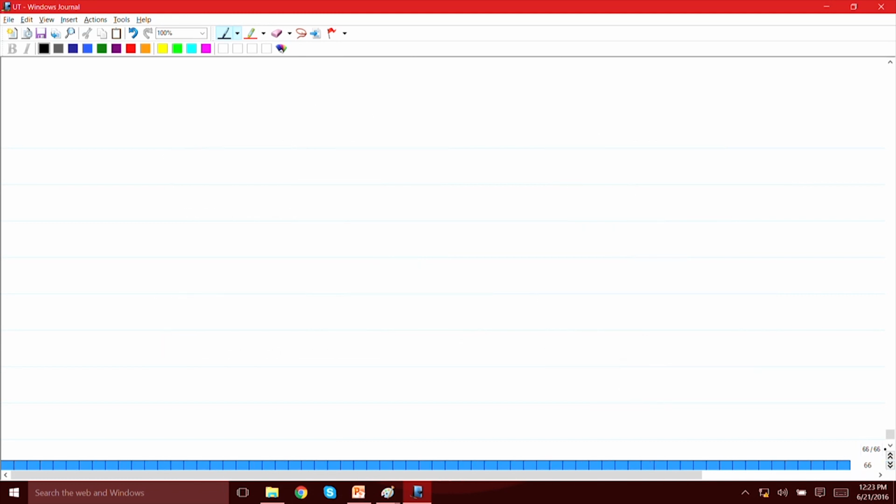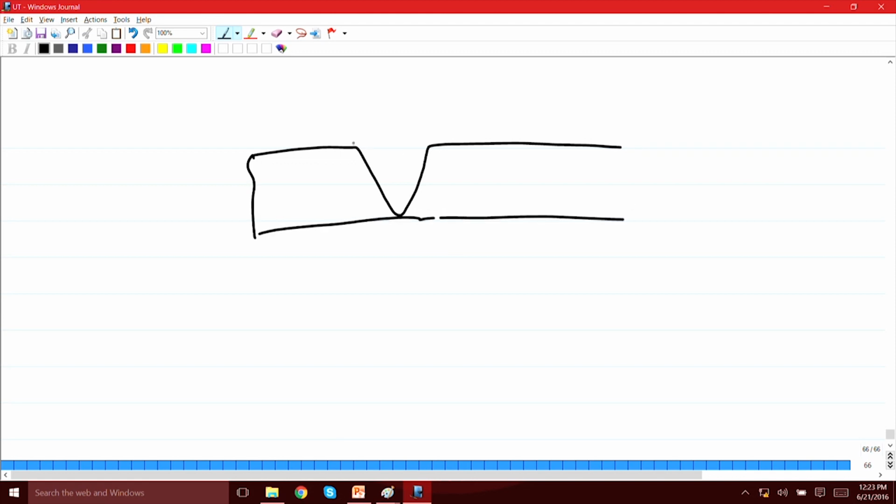Okay. So if you have any defect inside the weld, let us say over here or over here, then when you keep the probe at the half skip, it goes to the root, and as you move away from the half skip, let us say in between half skip and full skip, it can go and encounter these defects which are inside the weld.